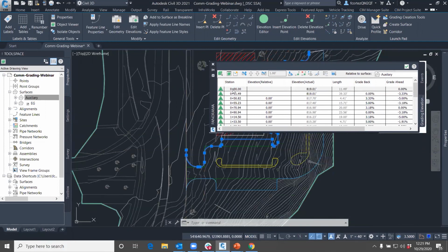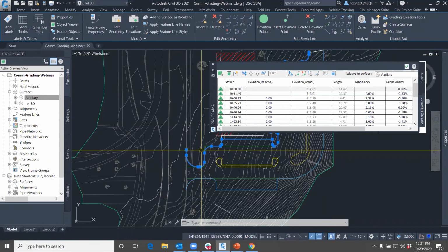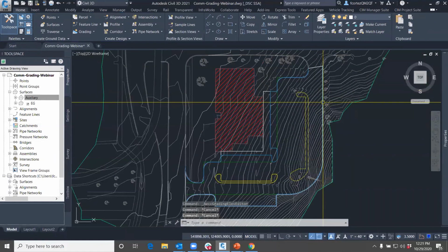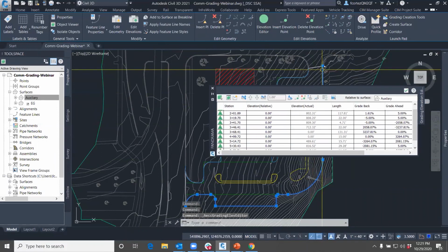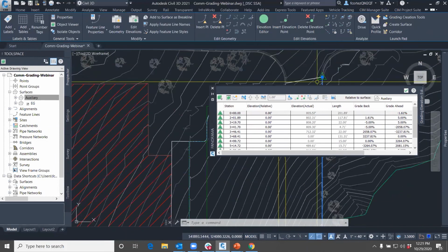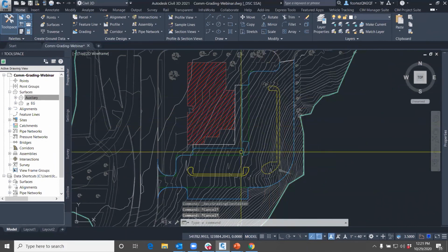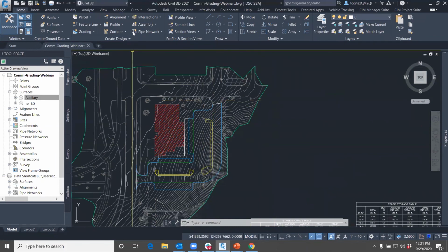That's telling us that's 0, which would mean our curb on our assembly would have to be on the left side to be outside of our flow line. And so that's fine now that we know that. And for our other feature line, let's go ahead and check that. So we would want our 0 to be up here, which it is. The reason we want to look at this before we start creating our assemblies is to see which side our sub-assemblies need to be on.